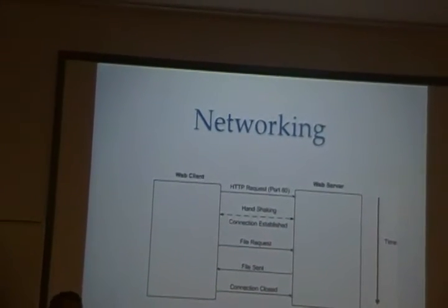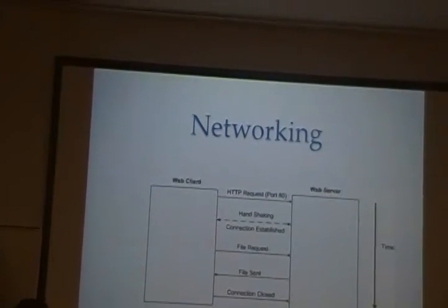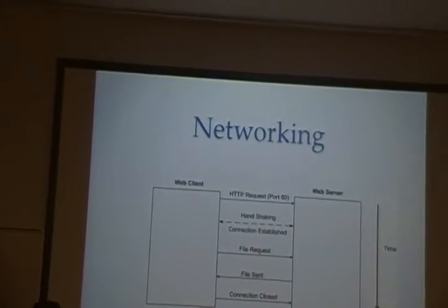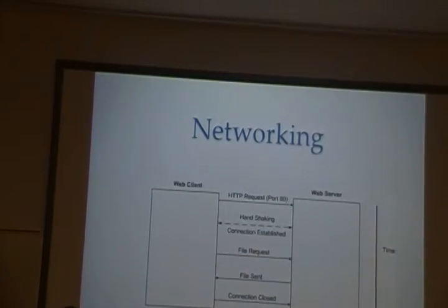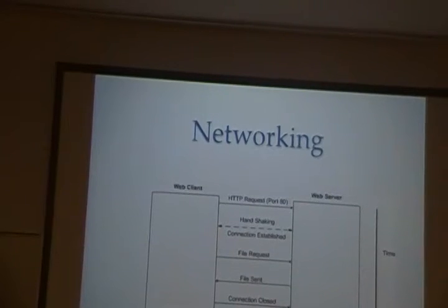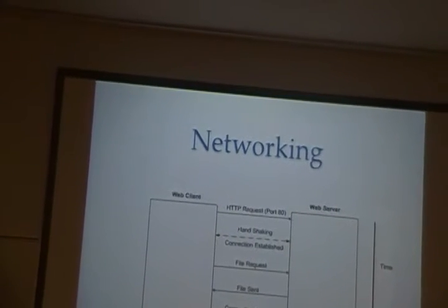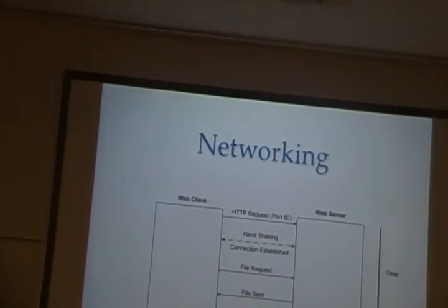So we programmed the microcontroller as a web server. Using a browser and the IP address of the host shield, we can send HTTP requests to the microcontroller. The request is first stored in a character buffer, and then separated to get a command and parameters that are needed to service the request.